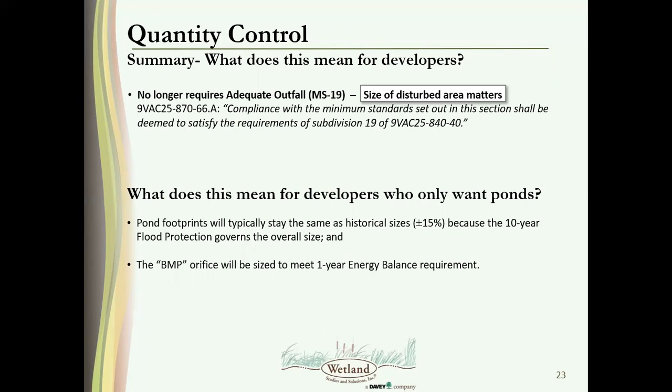Okay, so let's say you're a developer or you're working for a developer and they want to build their site, residential, commercial, industrial, whatever it's going to be, and they just want to keep using ponds. I've used ponds for 30 years. That's all I want to do. Well, okay, we can make that work. The footprints of your ponds are typically going to stay about the same because it's based on the 10-year storm.